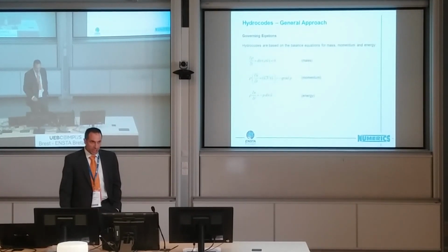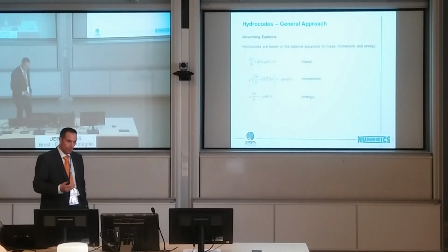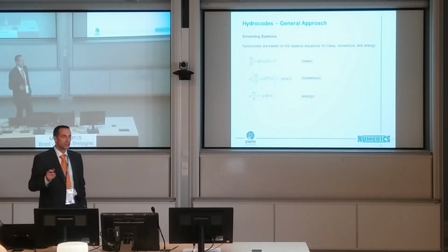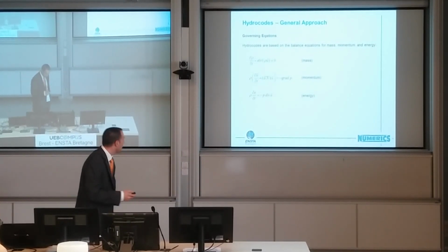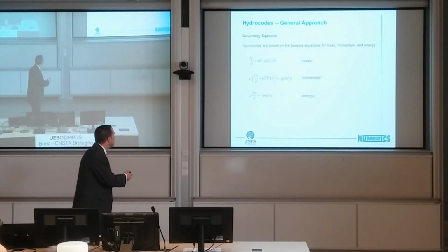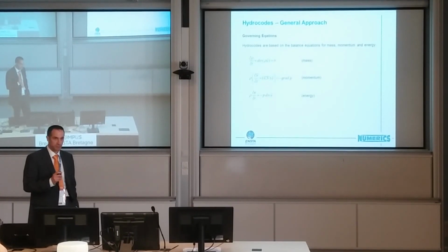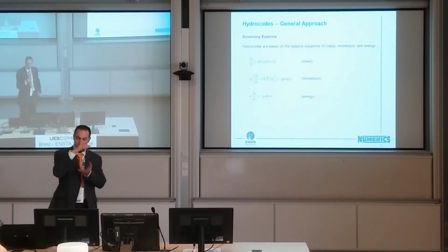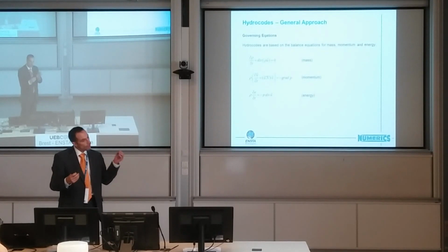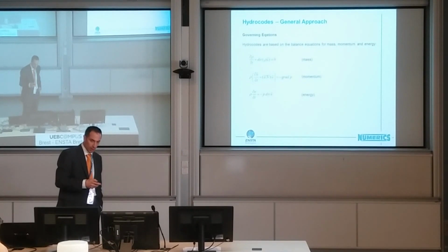So, governing equations. When we want to simulate this material going through the mesh, in hydrocodes, we generally build on the balance equations for mass, momentum, and energy. Everybody should have seen the three balance equations in some form at some time. Here, this is already the Eulerian description. So we are thinking we have a constant volume and we have material maybe going in and going out of our volume.